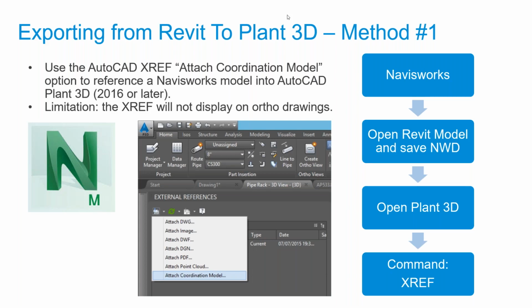But as you might know, in Plant 3D it's a bit hard to handle this Navisworks model. If it's a building, you need to open this building and save it in Navisworks, then attach it to Plant 3D. Then you could probably use it as a reference model where you can create pipes in this building, but it has to be open. So really, you cannot dive into a building as a DWG attachment in Plant 3D. That will not work well.